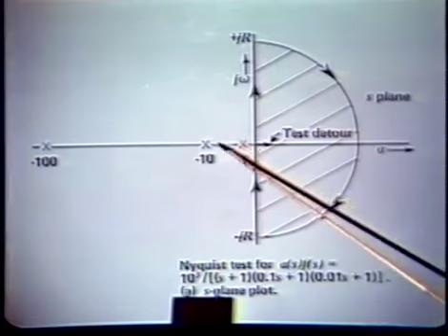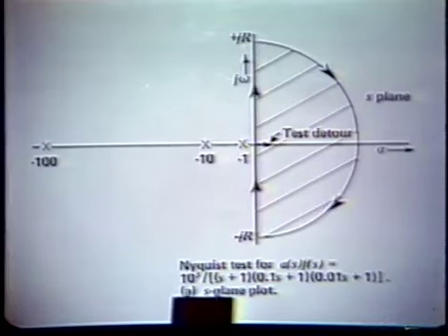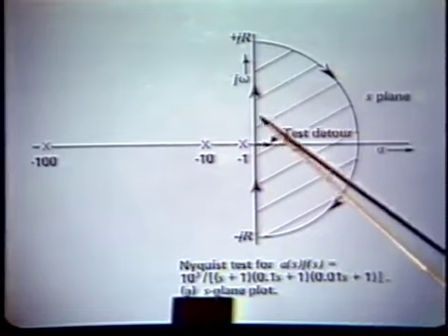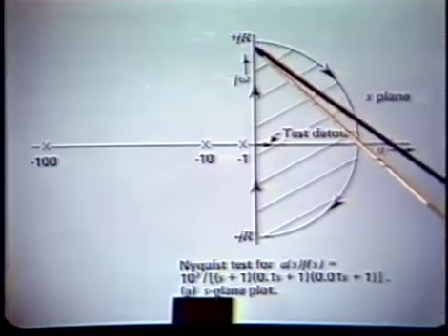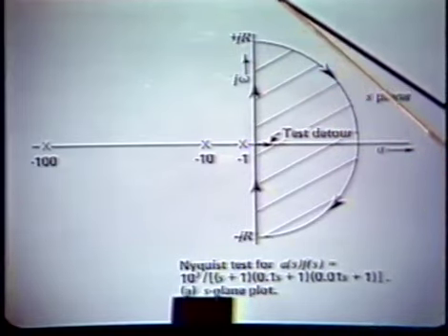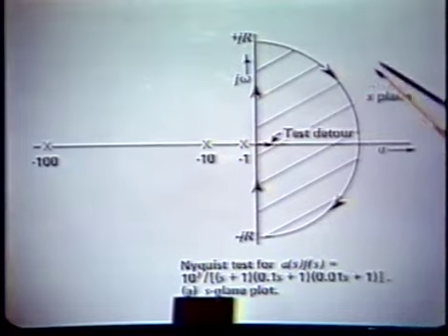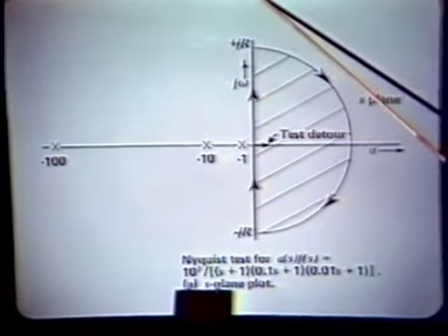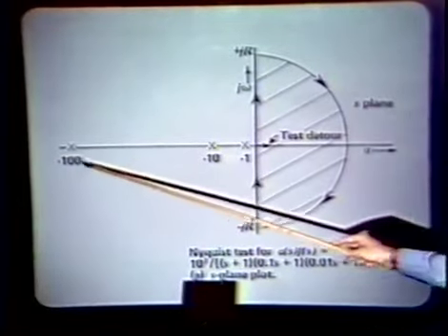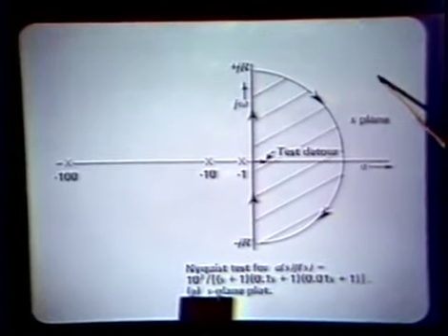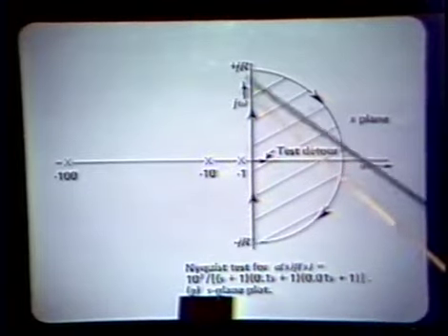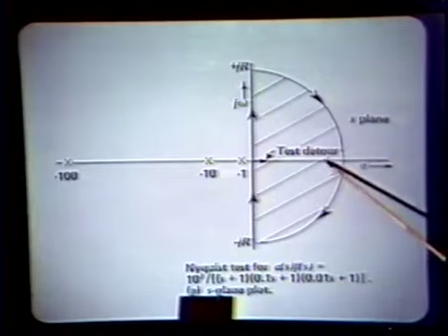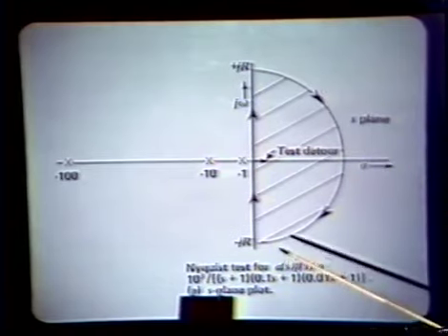We eventually get minus 90 degrees, of course, from each of the three poles. So the angle of the transfer function eventually approaches minus 270 degrees, 3 times the minus 90, once we're out to a very large radius and continue around. Why our magnitude stays fixed: if R is very large compared to minus 100, then as we close the contour, the lengths of these three vectors stay fixed as we go along a radius of capital R.